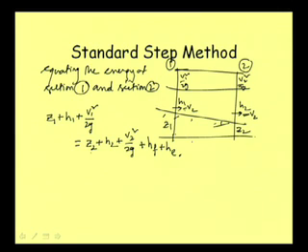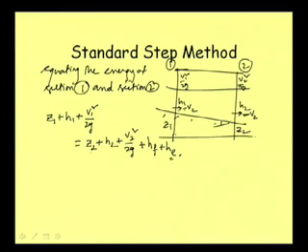If the channel is expanding or contracting, then this sort of eddy loss is important or significant. But if it is a prismatic channel, then this eddy loss is not that significant unless there is a lot of turbulence. And that is why in the direct step method, that was another reason why we cannot apply it to a non-prismatic channel. There we did not consider this eddy loss. Now, what is HF?